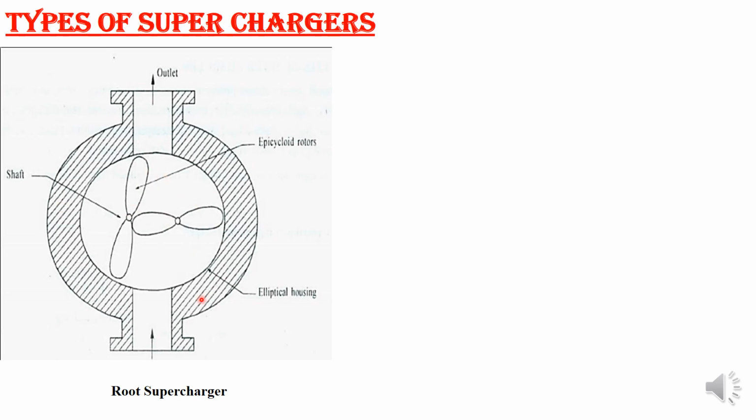Initially it will go over here and there won't be any compression. Whenever the discharge port is open, it will come over here, it will compress instantaneously, and it is going to the exhaust port. When the port opens, there might be a backflow of air, due to more work being required for compressing the air. Sometimes you may encounter backflow. Whenever the backflow of air is there, more work has to be done, that is, more work input is required to compress this air.